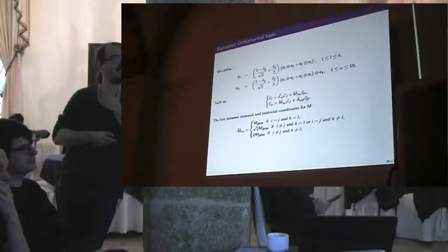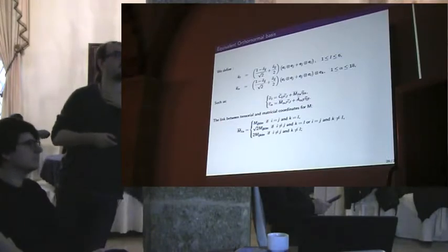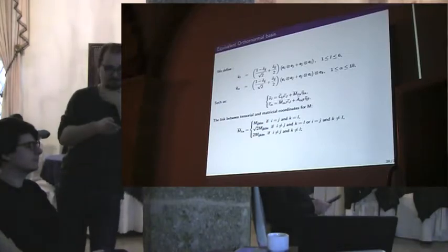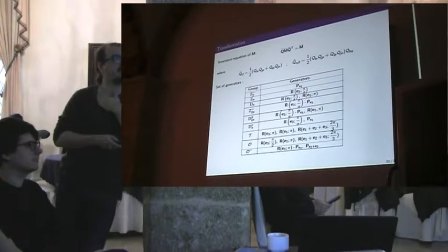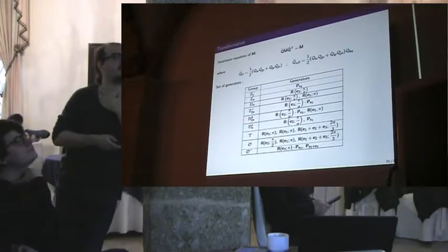So the elasticity tensor turned out to be a 6 by 6 symmetric matrix. The A tensor became an 18 by 18 symmetric matrix, and the coupling tensor turned into a matrix of dimension 6 by 18. With this rule and the associated conversion rule, it becomes quite easy with a formal computation code to determine the invariance restriction imposed by any elementary group.